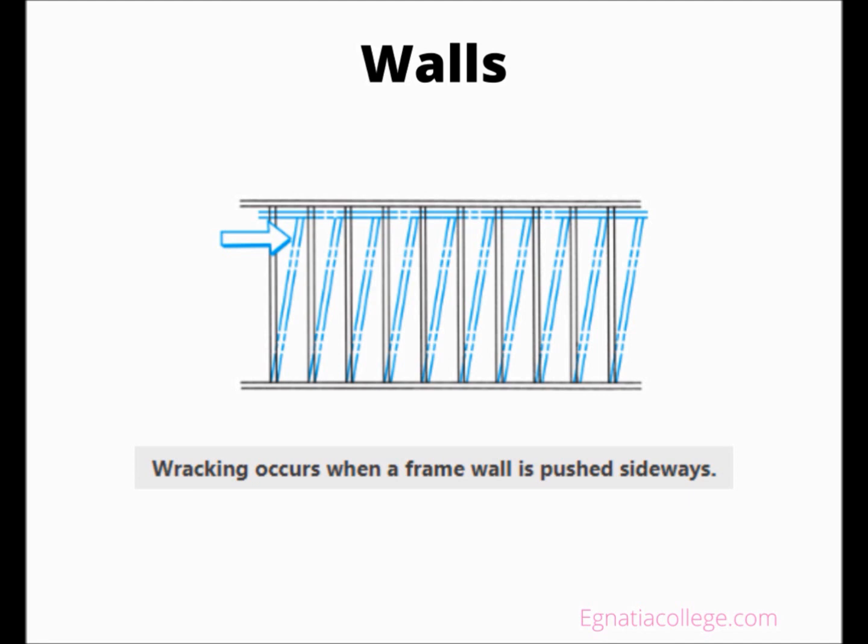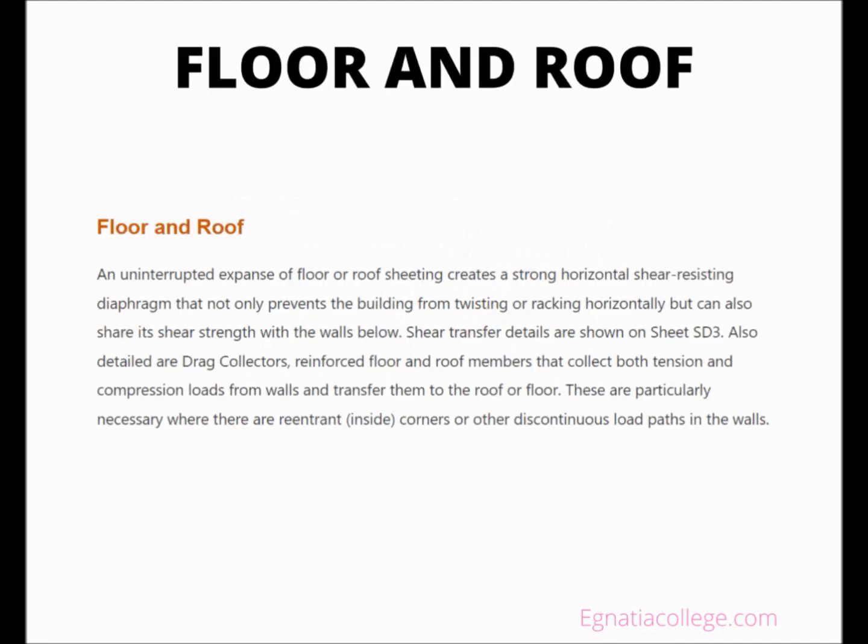On sheet S7.2, there are references to strap hold-downs connecting each story to the story above, holding the building together vertically and transferring shear from floor to floor. Details of these connections, including the straps, are included on sheet SD2.